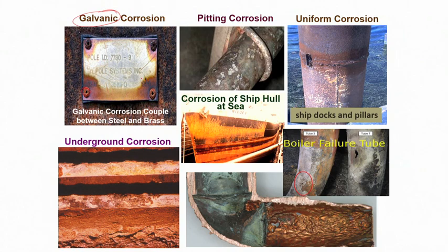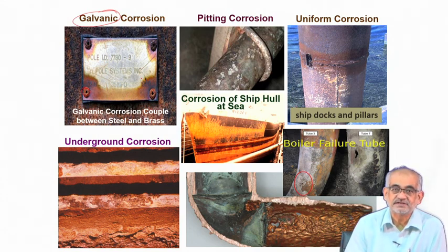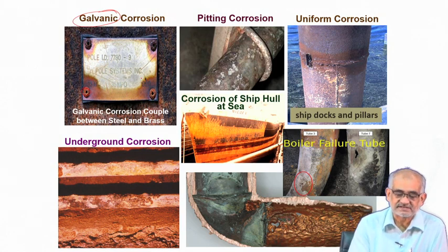the differences in its structure and specific volume, that means per unit mass, the crystal structure is such that the rust, or iron oxide or iron hydroxide, will actually expand when it forms, and hence creates enormous stress at the interface between the metal and the hydroxide, and gradually the rust, we all know, will spall off. And when the rust spalls off, then fresh iron is exposed and that gets oxidized and the process continues. So we keep losing a lot of iron from the surface as rust.